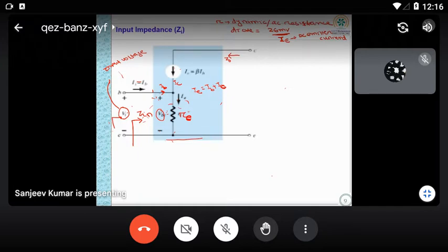So that's why you can see here it is written that the resistance value of this RE we can calculate as 26 millivolt divided by IE. And this IE is not the DC emitter current, not this small e. Are you getting me? Hello? Am I audible to everyone?